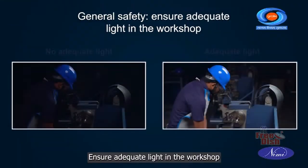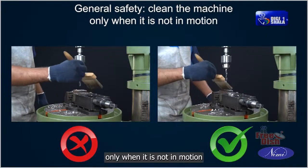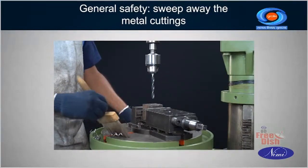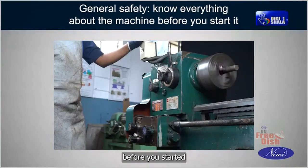Ensure adequate light in the workshop. Clean the machine only when it is not in motion. Sweep away the metal cuttings. Know everything about the machine before you start it.